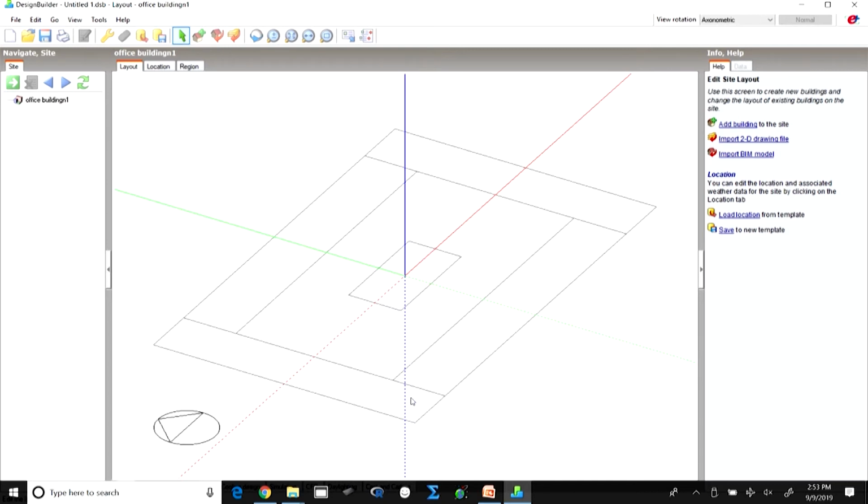If you remember our lecture where we were defining the perimeter zones, these perimeter zones are created to differentiate the zones which are right adjacent to the perimeter, because they receive different daylight. They also receive different heat stress because of being in proximity with the building envelope. And the remaining portion inside behaves differently as compared to the perimeter zone.